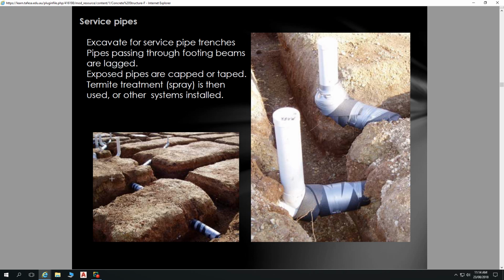And it's not always going to be picked up. Now, council do have to be notified before a footing pour happens, so they can get in there and check all that stuff. Whether that happens or not, that's not guaranteed. But yeah, it's important.